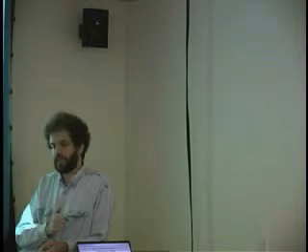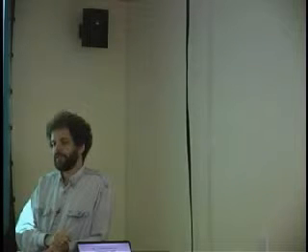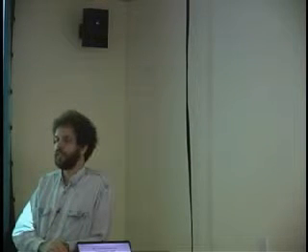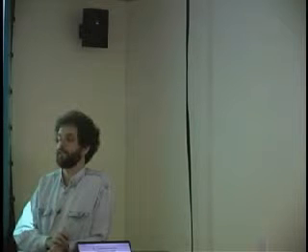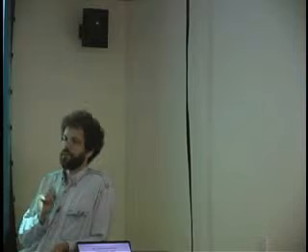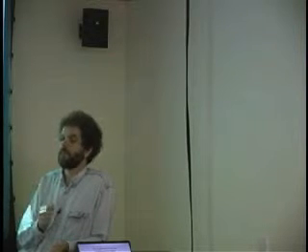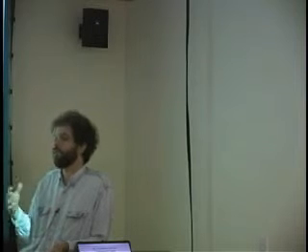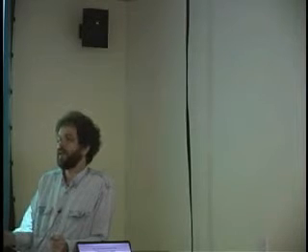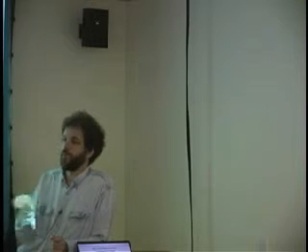And I guess the point I'm trying to get across is, in general, designing asynchronous fundamental mode state machines with feedback that does not have a synchronizing delay element is a very difficult thing to do, and it's a very difficult thing to get right. And so what we're doing here is, first of all, we've narrowed the problem down to be almost the most trivial state problem that there can be. Remember a 0 or remember a 1. And then furthermore, in order to do it, we're going to establish all of these very strict conditions saying don't try to do it while things are changing. And then the circuit we're going to use is going to be such that if we obey all of those rules, then we can prove that it's going to work because it won't generate this glitch. And then we can see that the feedback is going to work.